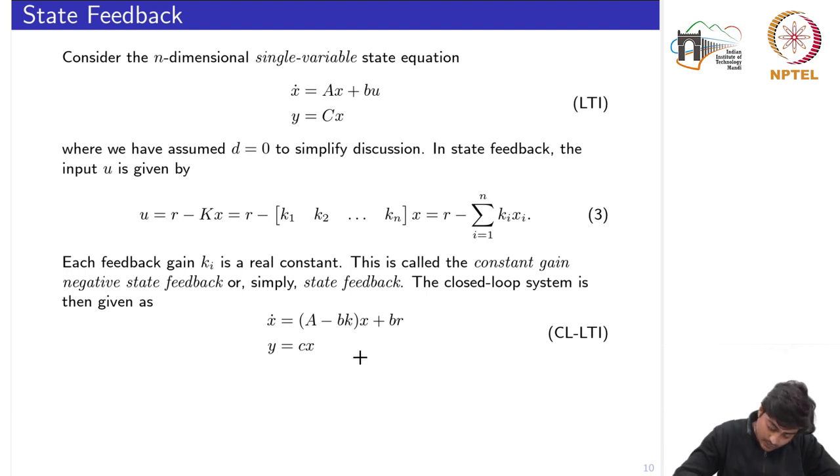So what we want to implement, if we see the state space description, is the integrator 1 by s, with x dot being the summation of A times x and the gain vector B times u.